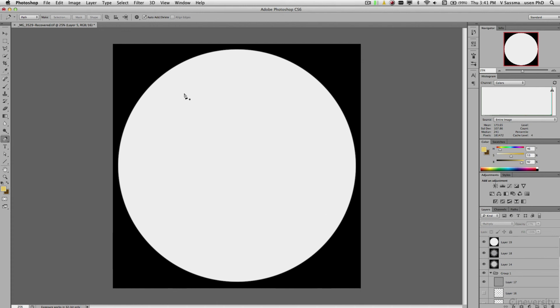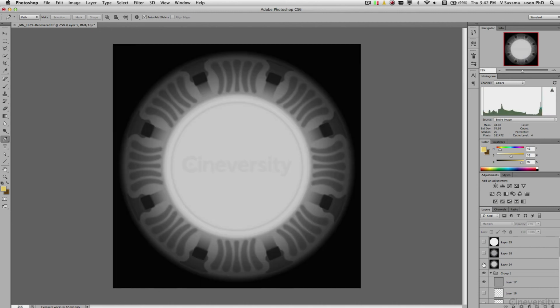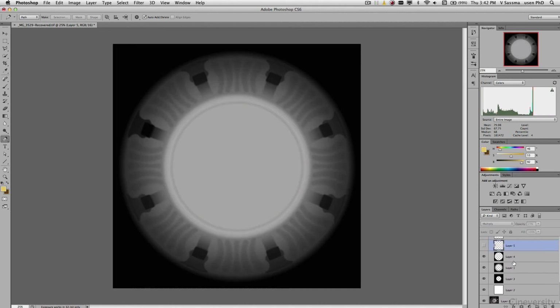Merged it and saved it out, so we don't have all these layers in Cinema 4D. The idea is, of course, before you merge everything, that you have for every tiny little detail here then just an opacity that fits exactly what you want to have, so you can adjust the height finally. And when you have a good base here with the black, the gradient, and here in the middle that area, then you can adjust exactly how high these parts finally go or how deep they go.